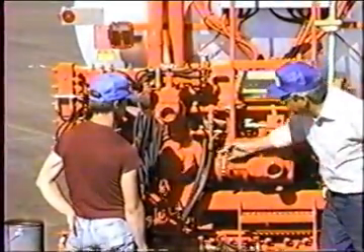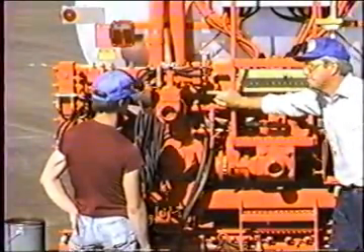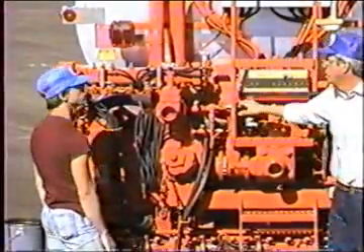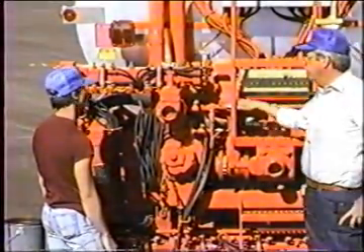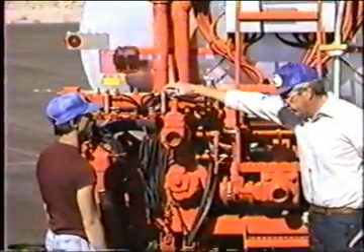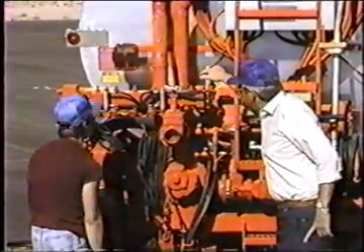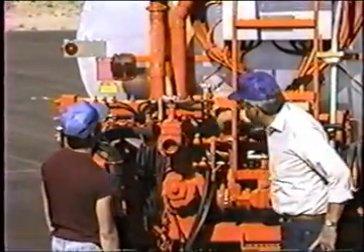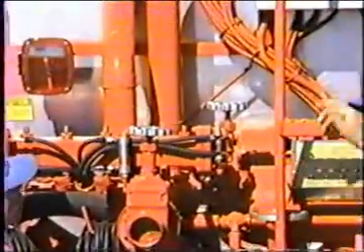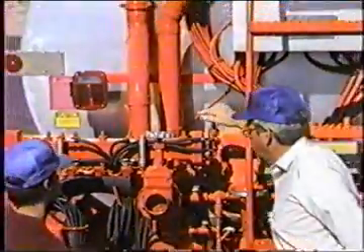So since we're going in the bottom of the pump and out the top, that means that we've got to run the pump in the forward direction. Okay, in the bottom, out the top, so we're forward. Once we get on top here, the asphalt's got 3 ways that it could go. It could come out this valve. I want to have that closed so it doesn't get all over us and make a bad mess. Okay, it could go this way to this valve. That goes to the spray bar. In fact, that's labeled spray bar right here. Right now we're just circulating the tank, so we don't want it to go to the spray bar, so we would close this valve.